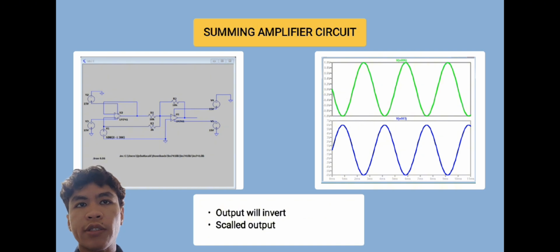So for our last circuit, it is the summing amplifier. In the summing amplifier circuit, we use two op-amps, one as a voltage follower for isolation and the second one as an inverting summer. The components we use are R1 equal to 10 kilo ohm, R2 equal to 2 kilo ohm and Rf equal to 10 kilo ohm. Both inputs at 1 Vp at 30 Hz give exactly negative 6 Vp output, confirming Vout equal to negative (V1 plus 5 V2). The circuit accurately performed the summation.